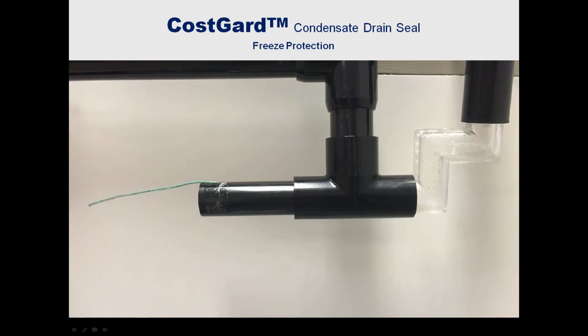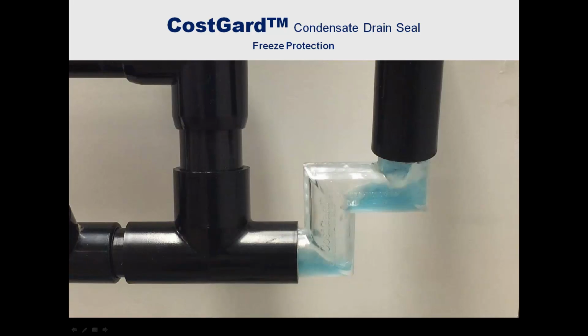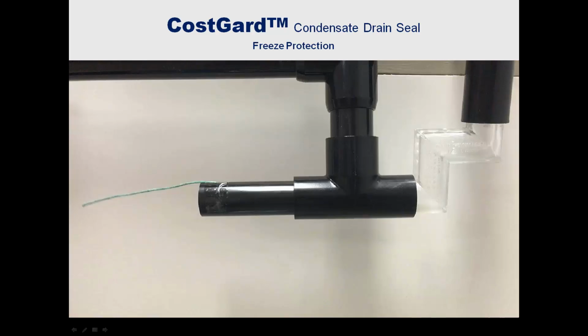Unlike the condensate trap, the CostGard condensate drain seal retains no condensate and is unaffected by freezing temperatures that destroy traps. During the cooling operation, when condensate is being generated, it flows rapidly through the drain seal, including the mitered elbows. Once condensate flow ceases, the warmer air that forms the drain seal quickly evaporates any water that may be held inside by surface tension.